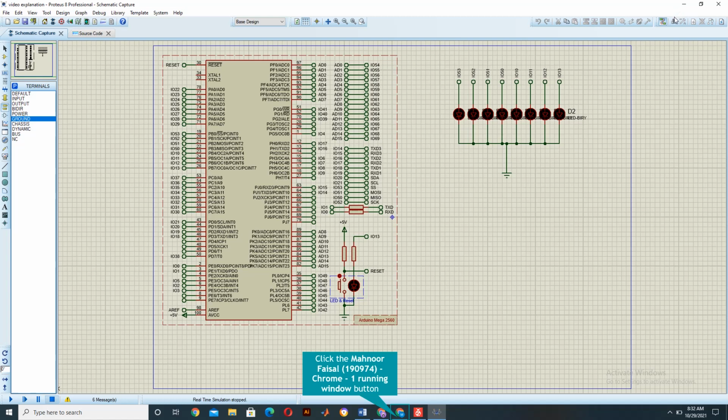These names are very important because when setting up the circuit, some of the pins are really difficult to find. If you just remove all of them, it would be very difficult to construct a circuit, because over here it is written as IO51, IO52, IO53. But on the Arduino Mega, it's very difficult to find which pin is port B1, because there it is not written as PB0, PB1, PB2.